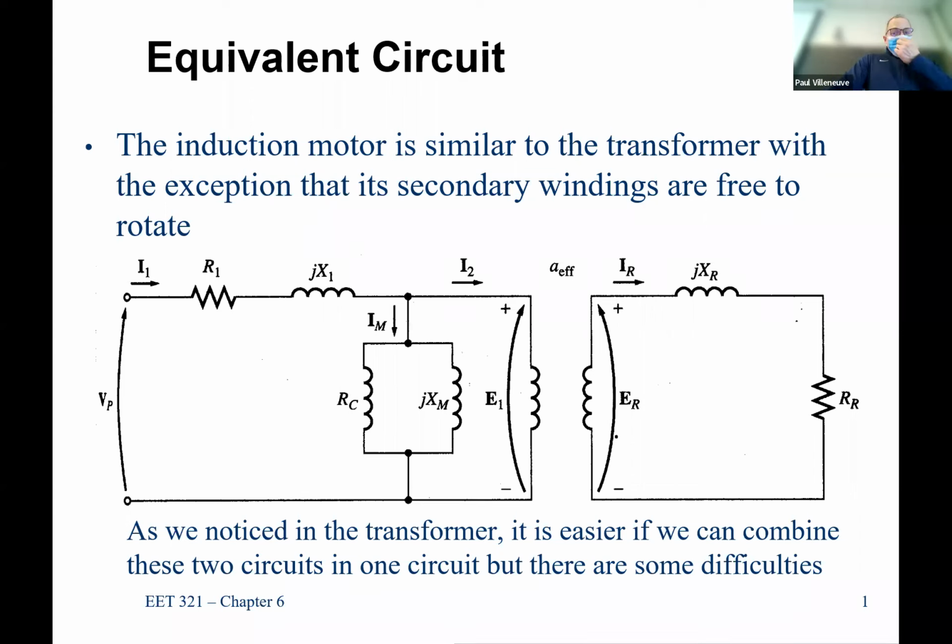All the power is going to be sent to the rotor circuit, which is going to get converted to mechanical energy. So the resistor that lives in the rotor circuit has to be adaptable so that it can represent the amount of power that is output of the machine. And if you had lab yesterday, we saw that the power output varied based on the speed of operation.